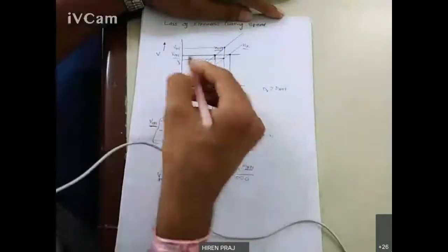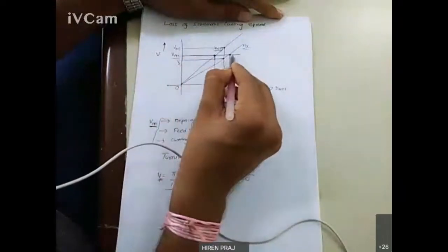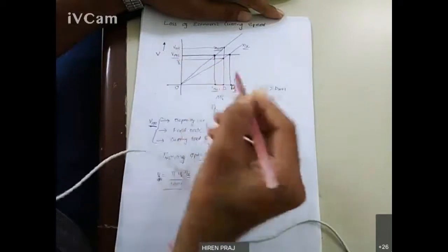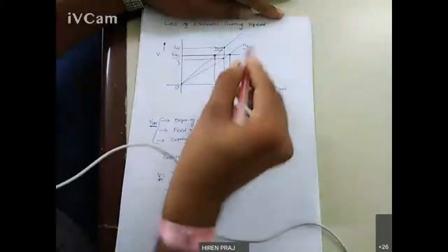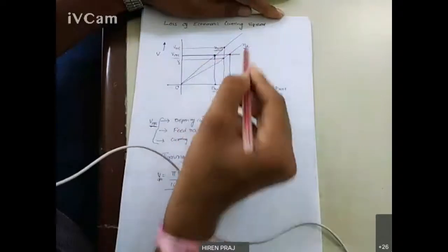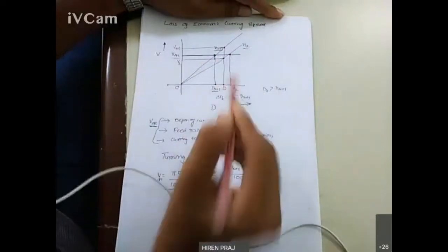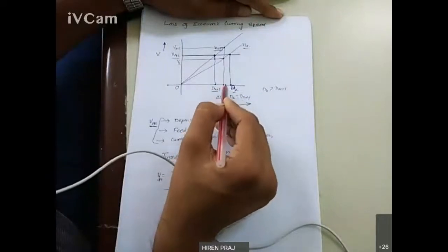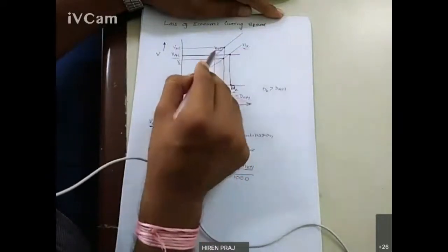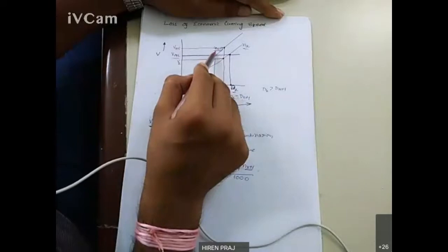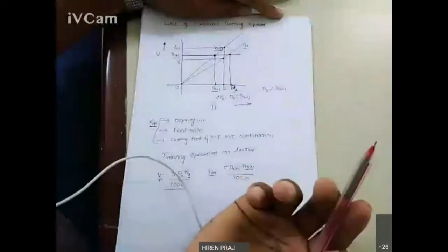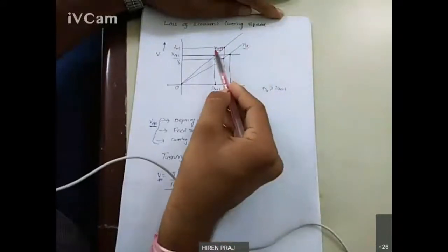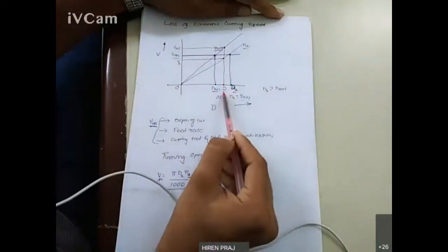So our requirement is actually V optimum, but this V optimum can be obtained for these two diameters only by these two RPMs. But if the diameter is in between these two, which is indicated by capital D, then, because I have only nx and nx plus 1 speed available from the gearbox, that is the limitation of the gearbox. It's a step drive. So either you can go for nx or nx plus 1 to do turning on this